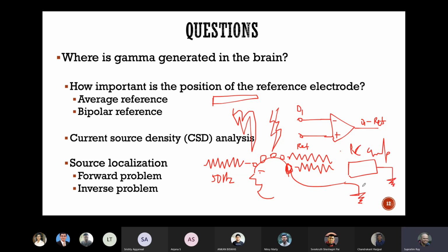What do we mean by ground? So often these are dedicated earths. We actually dig a big hole in the ground and put a lot of metal and charcoal and water and salt in that, and have a big copper wire, which then provides a dedicated earth to which we connect this electrode system. So only the most sensitive equipment is connected to that.